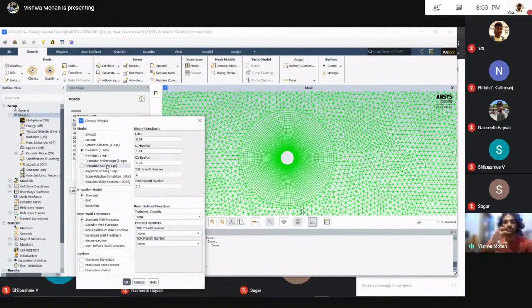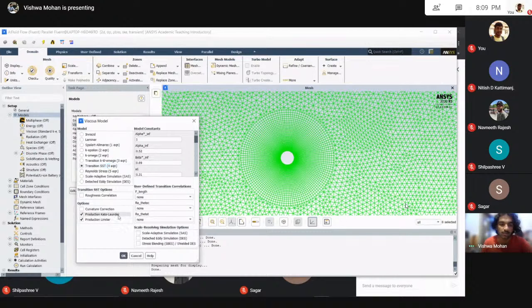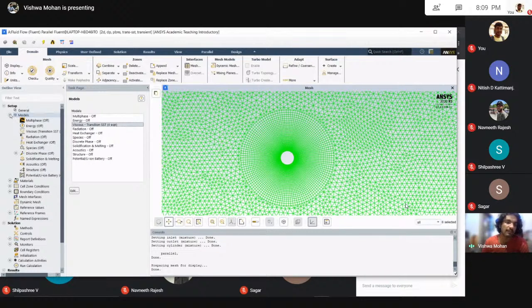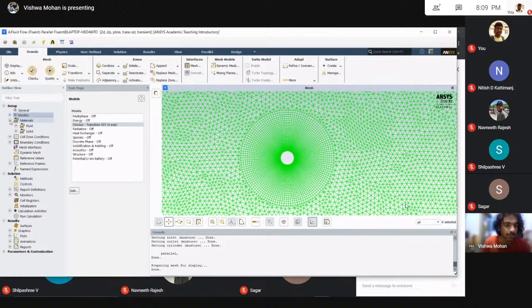The 4 equations, like in the model I showed you for the fluctuating flows, relate it to the turbulent viscosity and other things. There were 2 equations there for K epsilon, and for this we have 4. So we'll just select that and hit OK. It's very simple from here on, because it's GUI and you don't need to code. So that's done. Let's go for the material.